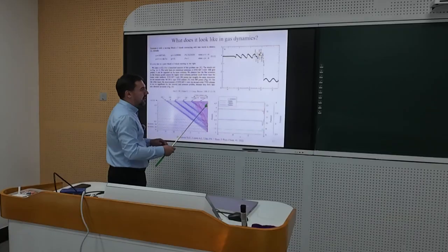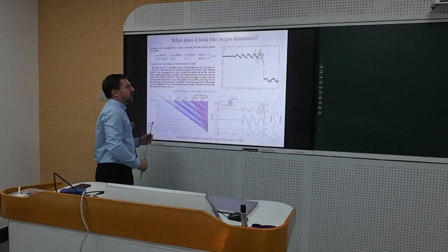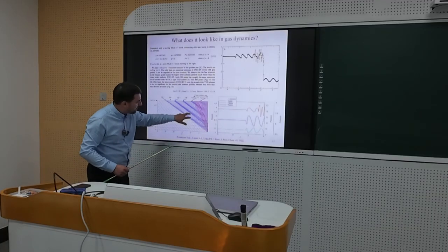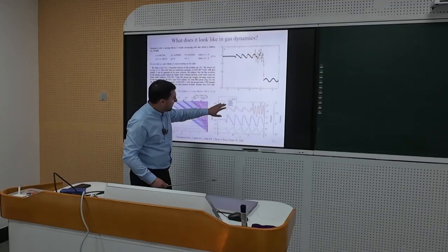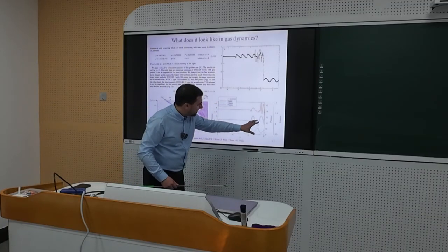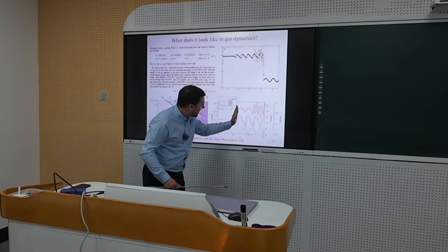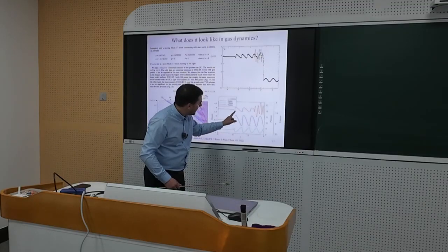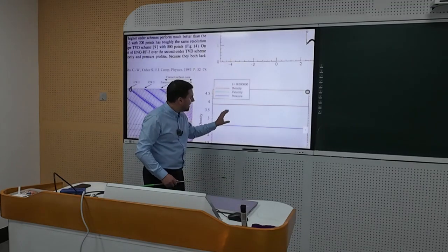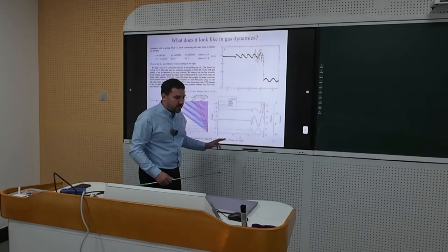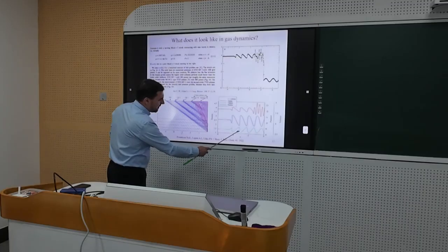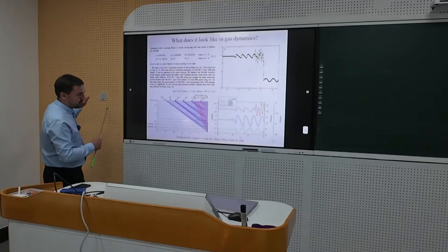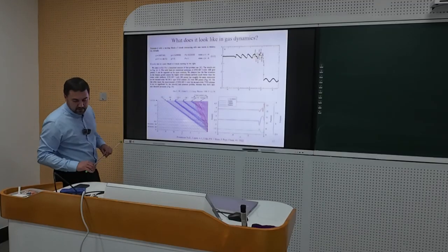We discussed what a Mach number means, and a realistic wavelength of this disturbance, and you can see the convergent and divergent characteristics. How does it look for density, velocity, and pressure? You can see some oscillation behavior, but this front becomes steeper and steeper. You can see it becomes sharper, sharper, and sharper. And actually, this is the mechanism of formation of a shock wave in real gas dynamic simulation. How they become sharp. And the mechanism is just the same as we just discussed for the scalar conservation law, right?